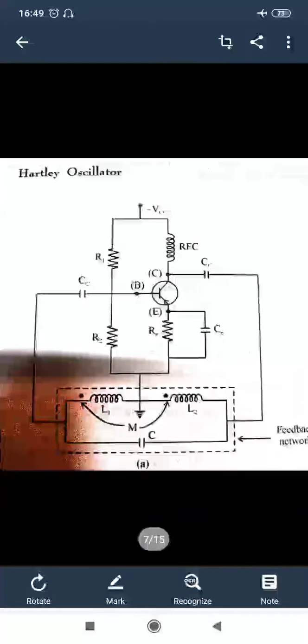For this we have used the equation. First I converted this circuit into the H parameter equivalent circuit of the transistor, the low frequency circuit model. In this case we have hie, hre, hfe and hoe. But here I have directly converted the current source into a voltage source equal to hfe I1 upon hoe, with a series resistance of 1 upon hoe.